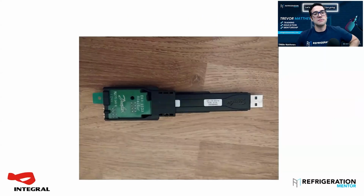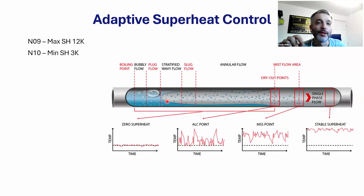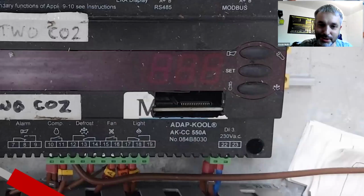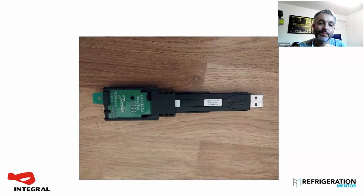If you're programming a lot of Danfoss cases for a startup or something like that, that saves you hours. So that programming tool, which is not super expensive, fits in the slot on the controller where your communications card fits. You pull out the communications card, which is just under that sticker there, carefully, preferably using the little hole in the corner so that you don't bust that chip that's right near the top of it. And then the programming tool slides into the controller.